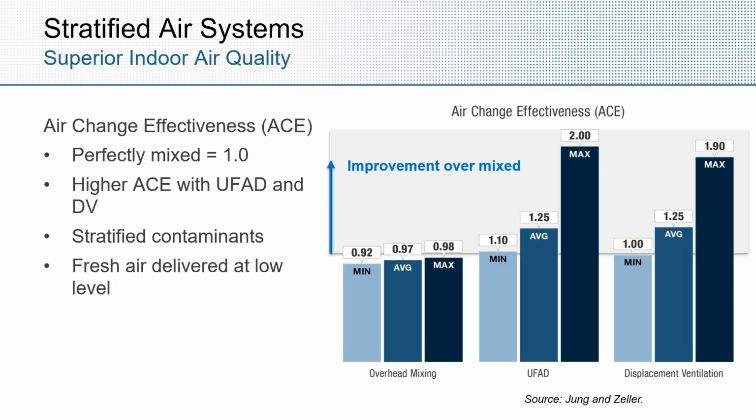As you would expect, especially from that video, the supply air gets to the breathing zone quicker than it gets to the return zone. So this is noting about a 30% improvement in those travel times by the UFAD, or underfloor air distribution system, and displacement system compared to a mixing system.